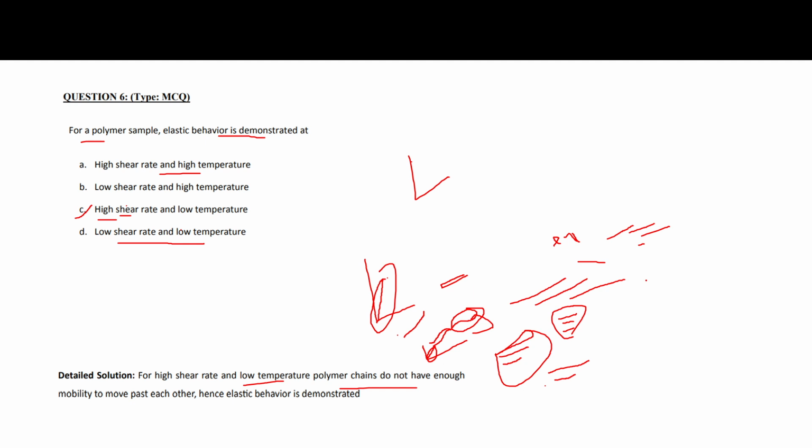But in elasticity, whichever path it is deformed along, it will go straight back along its line when you load it. It should be maybe that loop. If you go loop-wise, maybe that will be the hysteresis loop, but the loop width will be very low for an elastic material.